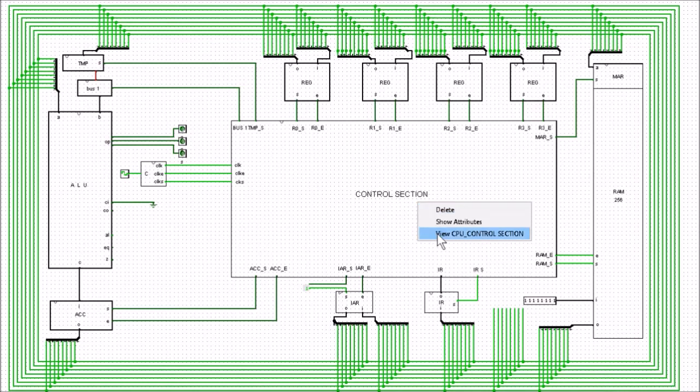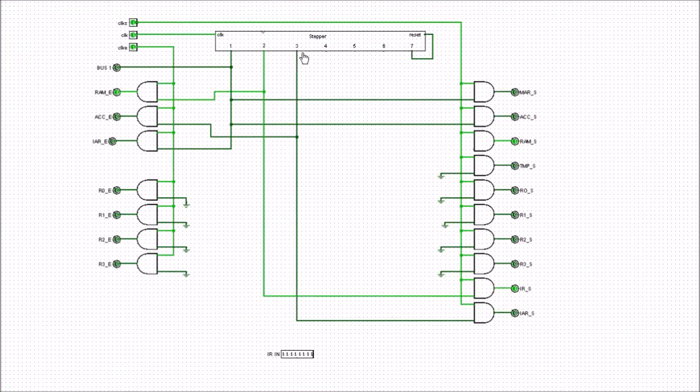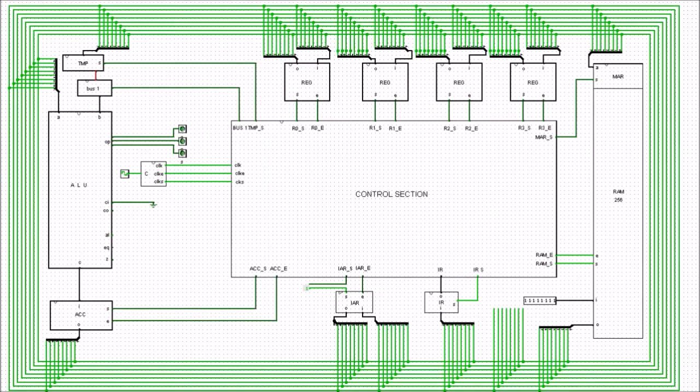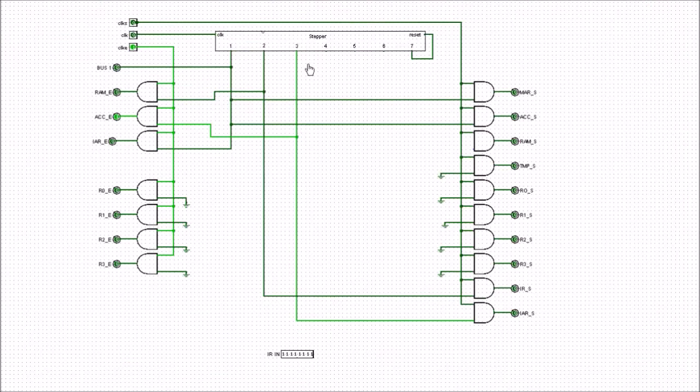So finally, there's a couple of loose ends to tie up. The next one is 0.3, so let's go along to 0.3. The next enable clock comes in, and at that point the accumulator gets enabled and the instruction address register gets set.